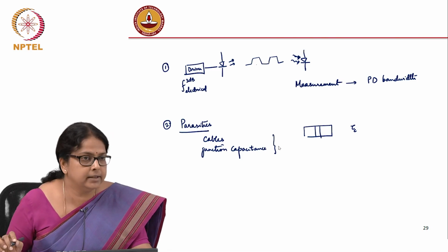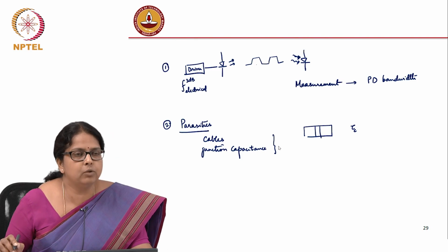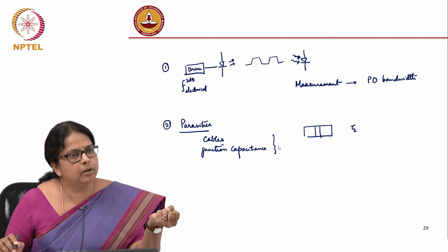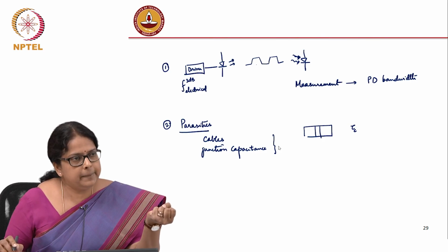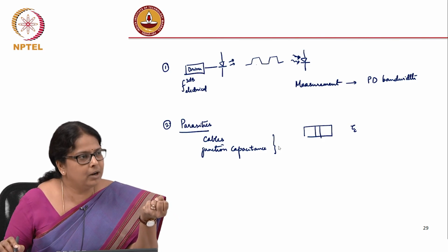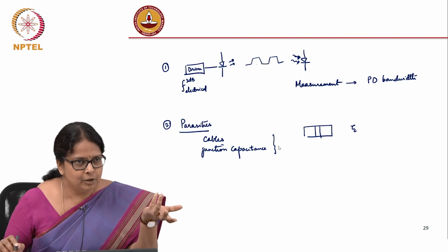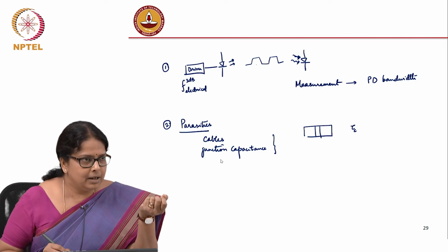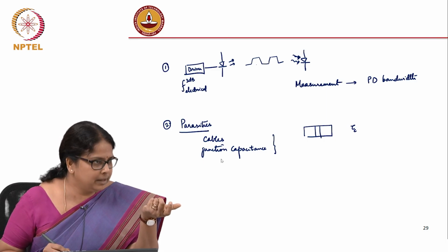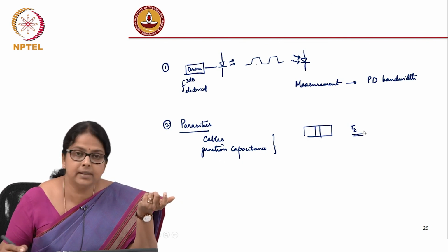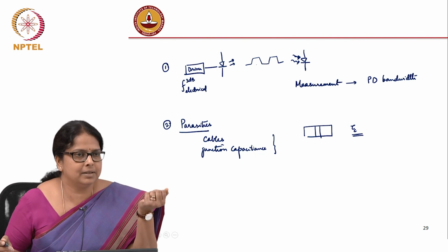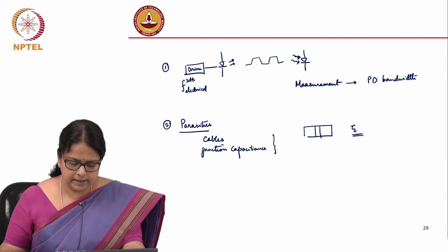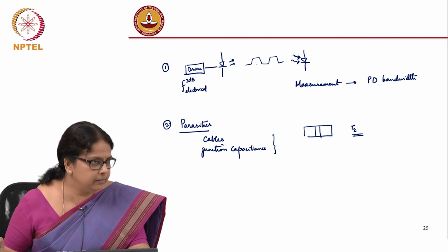etc. are not considered here, because when we just say 1 by √3 divided by 2 pi tau C, we are only considering the fundamental limitations because of the recombination time. But typically that number itself is so small, the bandwidth is only 5.5 megahertz. So, typically the cable capacitance, if you use a decent enough BNC cable, is not actually the limitation. The limitation typically comes from tau C itself, which is why you are not considering all this. Okay. So, that completes the electrical part, the modulation bandwidth part of the LED.